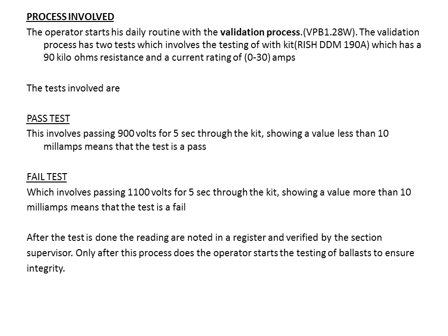The pass test involves passing 900 volts for 5 seconds through the kit. Showing a value less than 10 milliamps means that the test is a pass. The fail test involves passing 1100 volts for 5 seconds through the kit. Showing a value more than 10 milliamps means that the test is a fail.